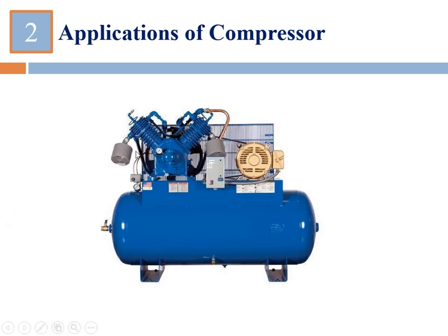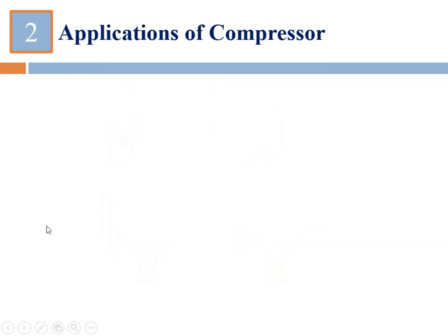Here these are the compressors, one is here, the second one is here. So this is a twin compressor, V in shape. This one is the motor which drives this compressor. The motor is not directly connected to the compressor, but it needs a belt drive, which you can see at the rear side of it, black in color, which causes the speed reduction. So the motor drives the compressor. The compressor compresses the air. That air gets stored in the tank, and then we utilize that air at a service station. For filling air in the tubes of tires, we use this kind of compressor.